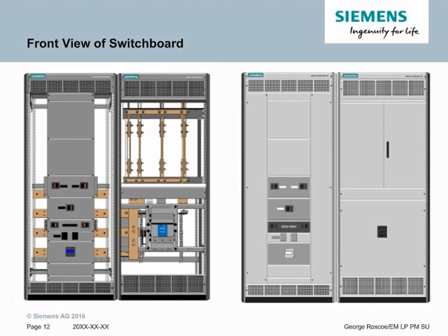The second section is a distribution section where you have several breakers mounted horizontally in unit space going from the through bus to the front of the gear, and have load lugs that can be taken out to feed devices outside the switchboard. This is a very common configuration and used in several thousand sections a year quantities.